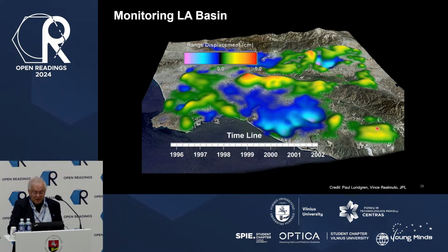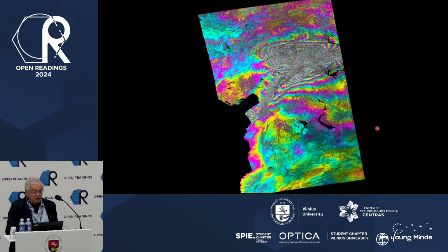You can measure that. And that shows you one example for the earthquake over Turkey, which happened about a year and a half ago, where you see these fringes, and every time you go from one fringe to the next, that means the surface moved a couple of centimeters. So actually, we're getting a picture of the earthquake itself, which gives you the pattern of how that earthquake happened. And also, it has the other benefit: where the fringes are very close, that means there was a lot of motion. And we usually send that information to the rescuers very quickly, because that's most likely where most of the damage happened in that area. So that gives you an illustration of some of these applications.